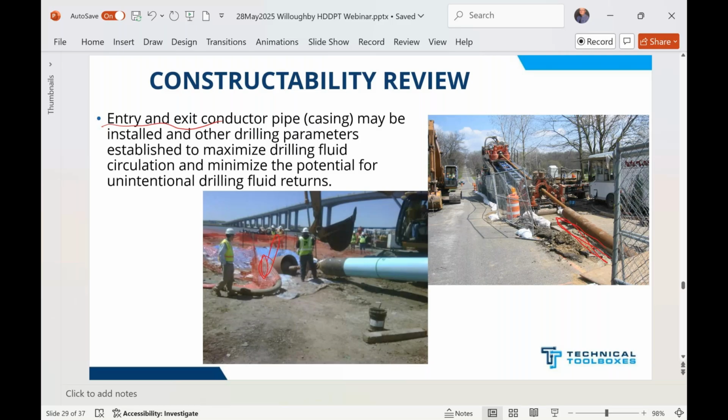Okay, normally on the entry side where the drill rig is, we'll try to go somewhere around 12 degrees going into the ground. That's just a rule of thumb. As the soil gets stiffer, harder, we'll use a steeper angle to make sure we penetrate the soil. If I have a rock ledge down here, then we'll make it an even steeper angle, maybe 14 or 16, because we want to hit that rock at more of a direct angle. It helps us penetrate the rock. So we never go less than 12, and we'll go up to 14, 16.